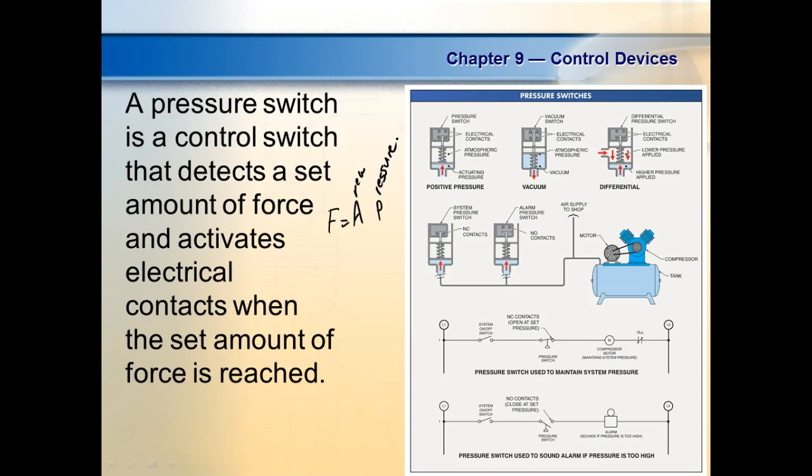So sensing pressure would tell us how much force we're going to be able to generate. It becomes important when you're using impact tools, moving robots around, or grippers, different tools that we found on our robot. So maintaining a good pressure really means something. So we have pressure gauges, we have pressure sensors.